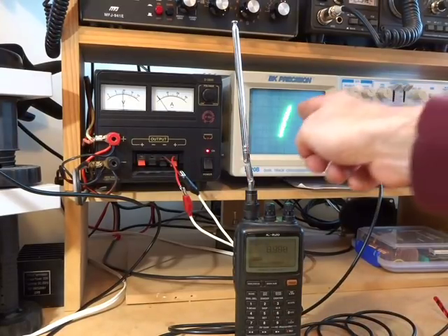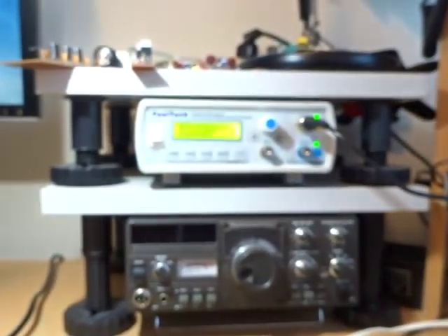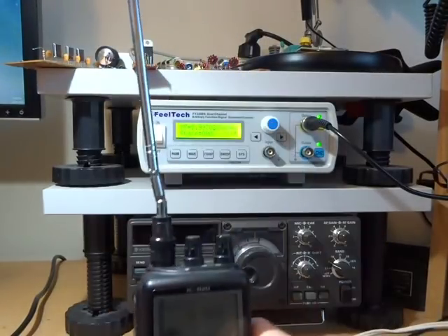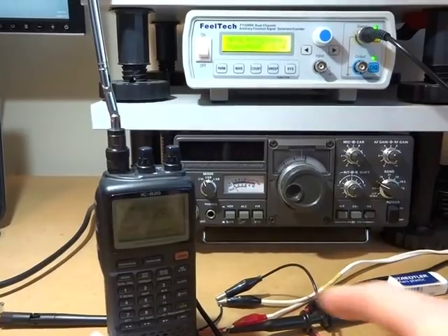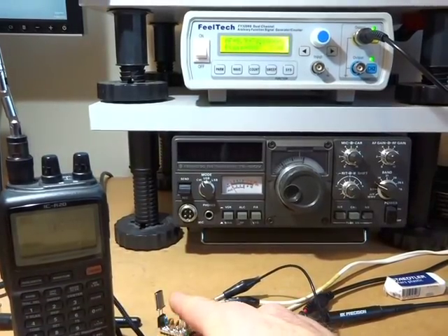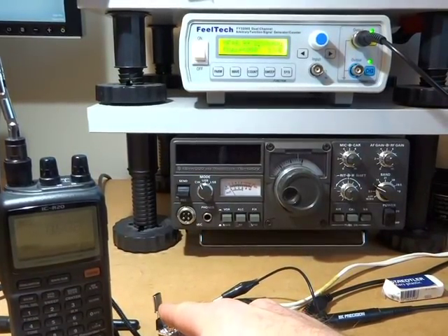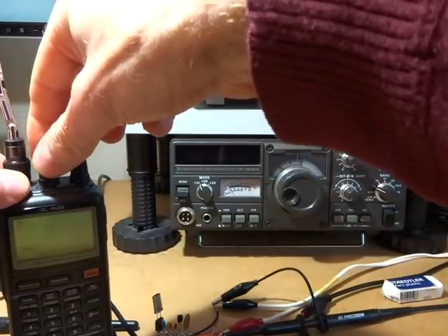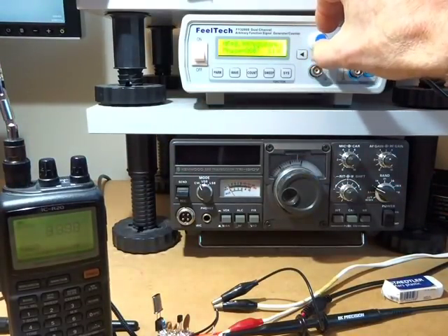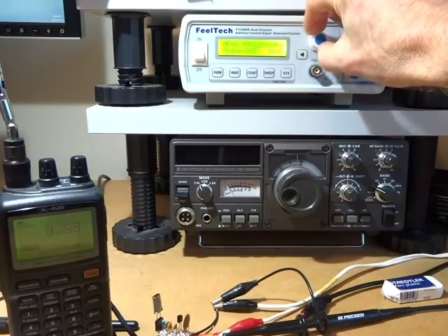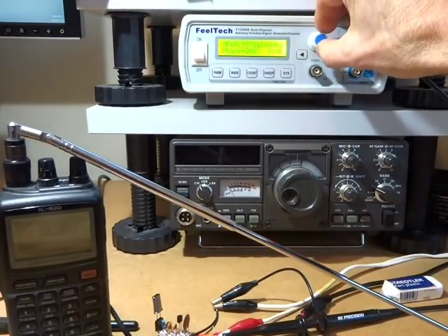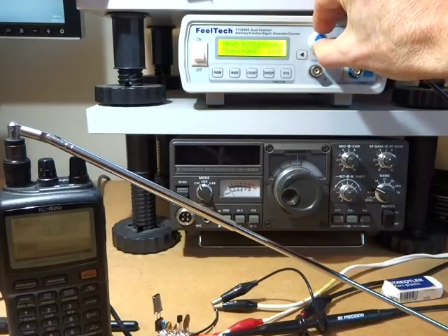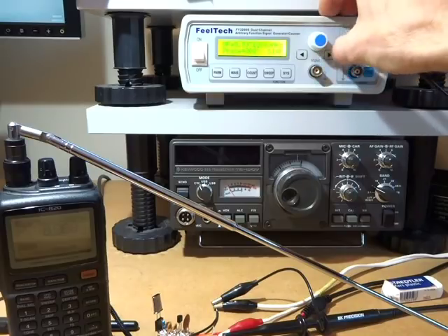So without the O-scope, what we could have done is used our SIGGEN here, and then assuming that this is our unknown, the crystal in our oscillator, by using this we could then tune for 0 beat. And it's better if that's near the SIGGEN. And then we can use the fine tune here.